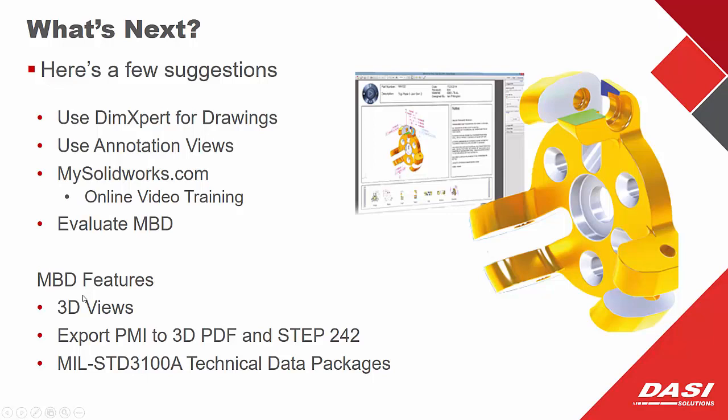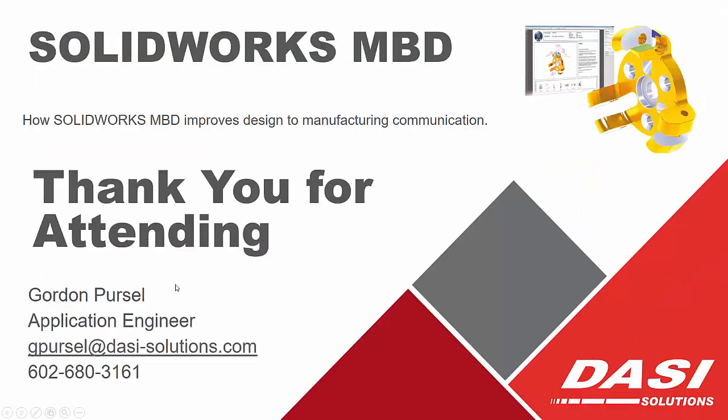MBD features shown today were really the 3D views, the model break views, and how it supports sectioning views, exporting all the PMI to 3D PDF, STEP 242s, and support for the MIL standard 31000A technical data packages.